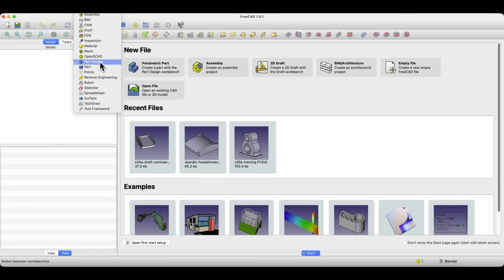For example, if you finish designing a part and realize later that you need to change a dimension, say increase a hole diameter from 10 mm to 12 mm, you don't have to redesign the entire model. You just change the relevant parameter and the model updates automatically. This approach is especially helpful for advanced users or 3D printing enthusiasts. If you print a part and it doesn't fit quite right, you can easily tweak a few parameters without having to start from scratch. As you can see, FreeCAD has a lot of advantages, and I believe it's a great tool for beginners.